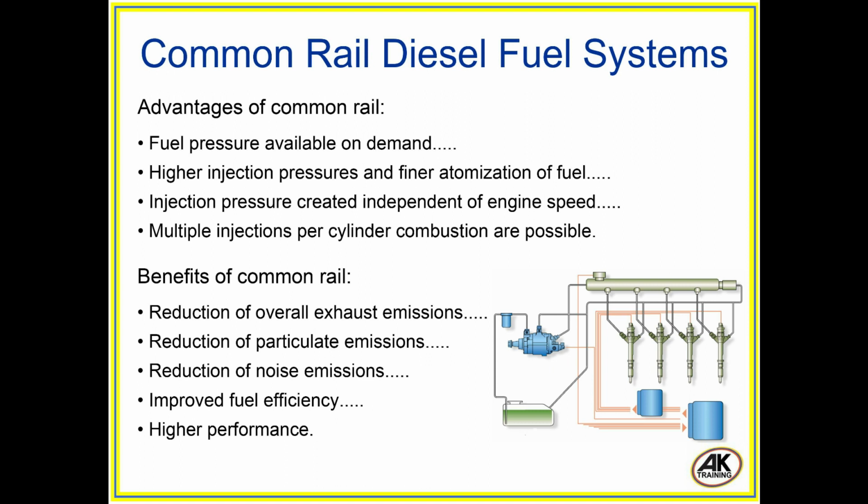Advantages of Common Rail. Fuel pressure available on demand. Higher injection pressures and finer atomization of fuel. Injection pressure created independent of engine speed. Multiple injections per cylinder combustion are possible.